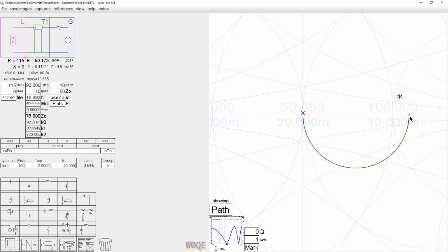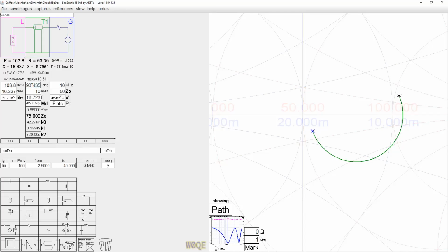But as I said before, we were going to drag the antenna that we actually built to somewhere up here. So now what happens? If I want to do nothing else but have a piece of transmission line here to give me the best match possible, well, I sure as heck don't want to stop this at a 90-degree rotation. The wise thing to do here is clearly to extend the rotation up to, say, someplace like there, 103 degrees. That's pretty far off from 90, but that's actually a better match. We can make this match even better if we want to. We can make it better by doing something.